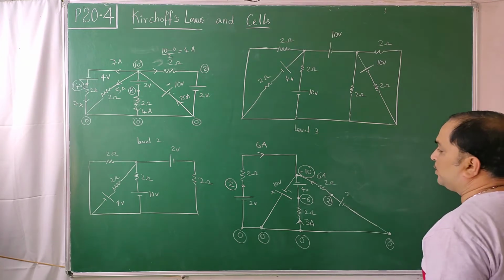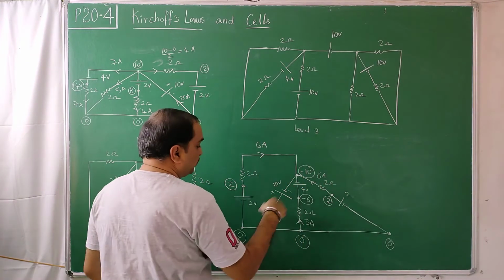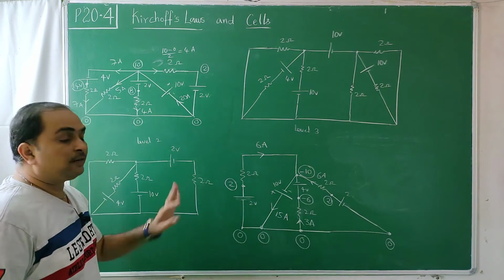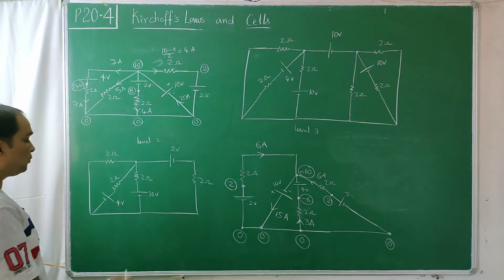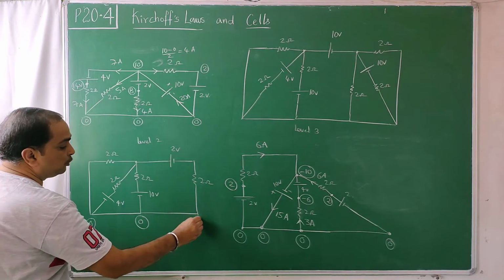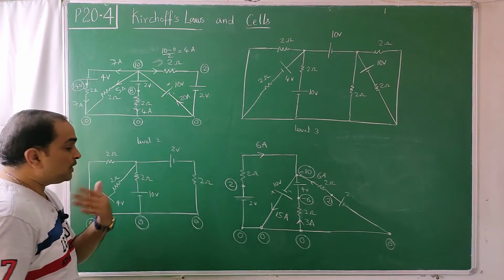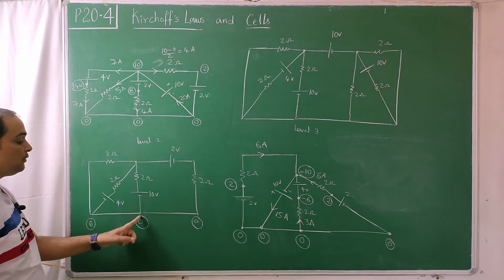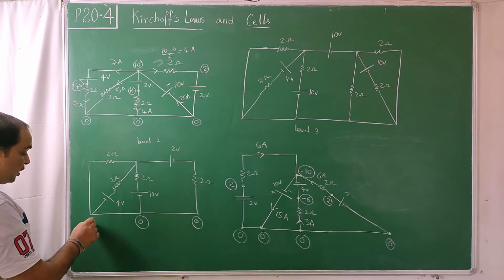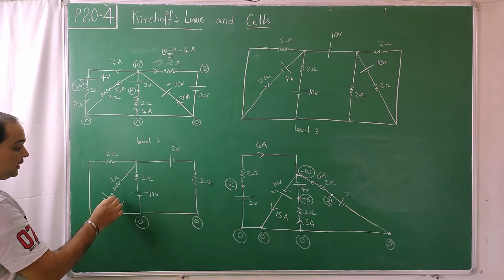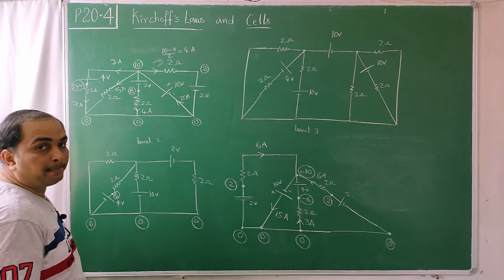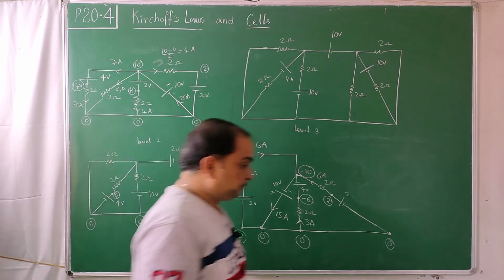So what about this? I told incoming, incoming, incoming. So this should be outgoing 15 amperes. Then I will take care of it. Now coming to this point. So if I take this potential to be 0, this potential to be 0, just by inspection, just by view, I cannot tell what is the potential of this point because everywhere resistance is coming in the middle. To some extent I can go from here to here and say there is a rise and this point to be at 4 volts. But this is not sufficient. Still I want this point. So what to do?